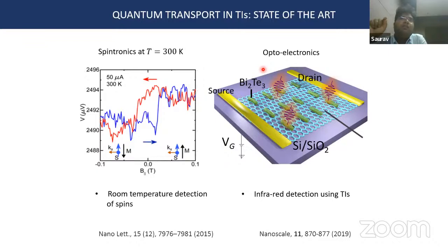I was observing a change in resistance of the graphene due to transfer of hot electrons to the graphene. Now, the temperature coefficient of resistivity, dR/dT, is higher in single layer graphene than bilayer graphene, at least. So if I use bilayer graphene, the sensitivity itself is going to get reduced. That's what I feel. I see. Okay, because of the nature of the mechanism of response in this context. Thanks for the answer.